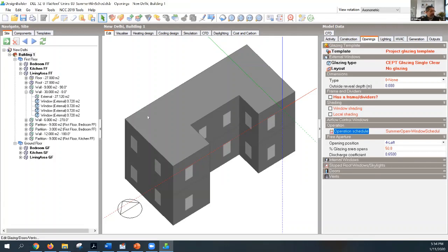So what I did was I drew a second roof on top of the first roof, about 1 meter above the building, just a thin roof which is shading the concrete flat roof of the first floor. And then I compared the runs of one simulation where I didn't have the fly roof and another one where I did have the fly roof on. So how do you do that?